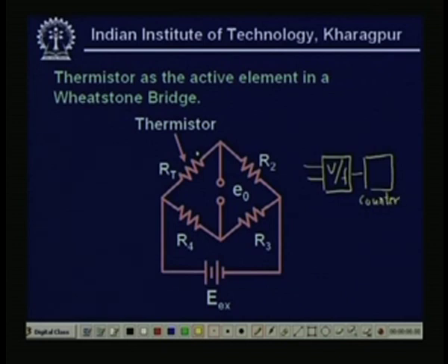It will simply measure the frequency, and the frequency will be calibrated in terms of temperature, degrees centigrade. The advantage of this, as I told you earlier, is that the resolution and sensitivity can also be increased, because I have signal conditioning circuitry where I can make all this type of manipulation, so that I get the frequency change more sensitive.